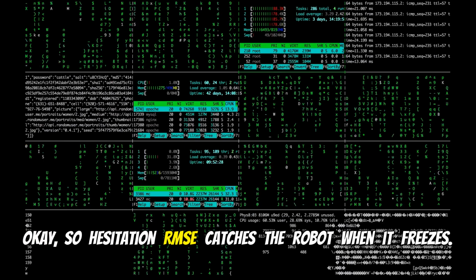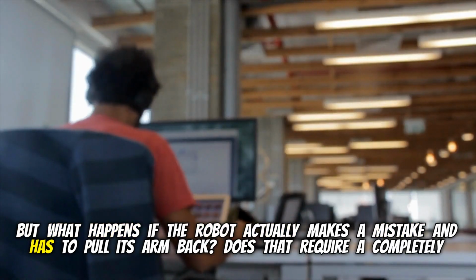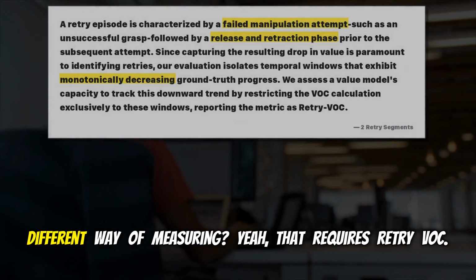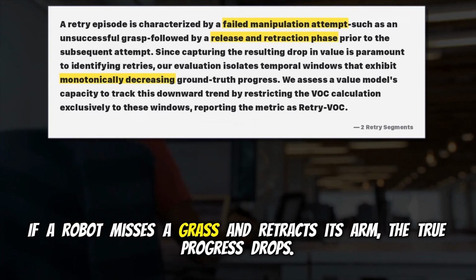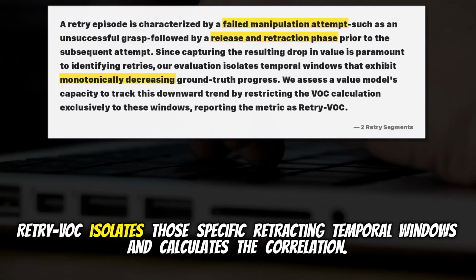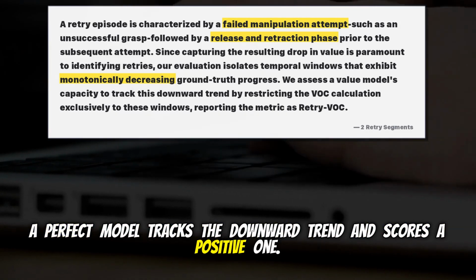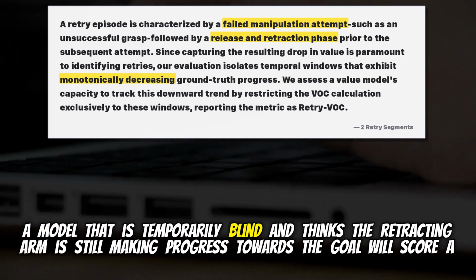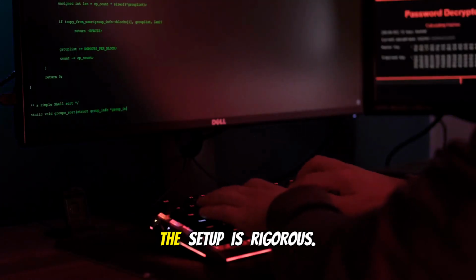Okay, so hesitation RMSE catches the robot when it freezes, but what happens if the robot actually makes a mistake and has to pull its arm back? Does that require a completely different way of measuring? Yeah, that requires retry VOC. This measures how well the model tracks a downward trend. If a robot misses a grasp and retracts its arm, the true progress drops. Retry VOC isolates those specific retracting temporal windows and calculates the correlation. A perfect model tracks the downward trend and scores a +1. A model that is temporally blind and thinks the retracting arm is still making progress towards the goal will score a -1. The setup is rigorous.